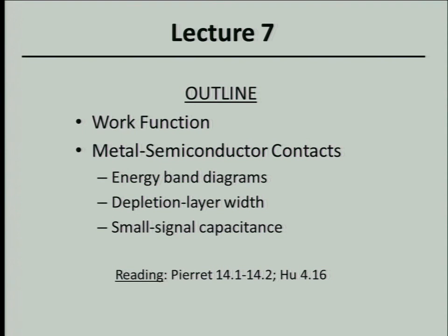All right, so a metal semiconductor contact might sound really boring to you, but actually it's quite useful, and it is important to understand how a metal semiconductor contact should be designed to perform the function that you want it to. In a semiconductor integrated circuit, we have metal semiconductor contacts pretty much wherever we want to conduct current into and out of a semiconductor device. If we look at a schematic cross-section of a MOS transistor, with the gate controlling current flowing between the source and drain regions, current flows into and out of the transistor through metal wires that physically touch the semiconductor.